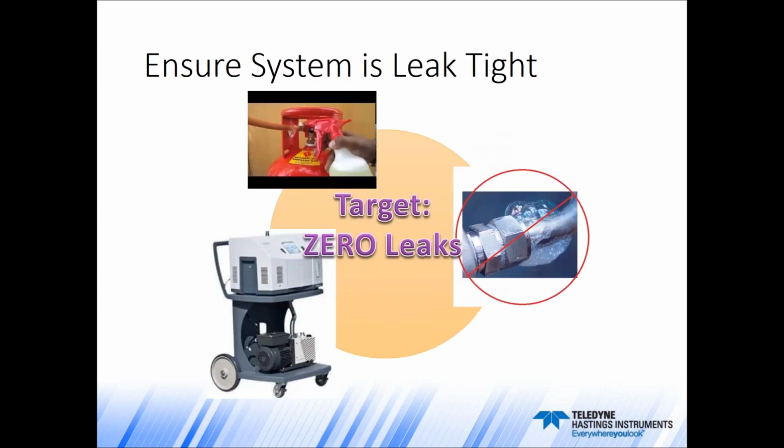All right, one last word about new installations. You want to make sure that all your system connections are leak tight. An easy way to do this is with Snoop or soap bubble, or if you have access to a helium leak detector, you can find very small leaks very quickly.